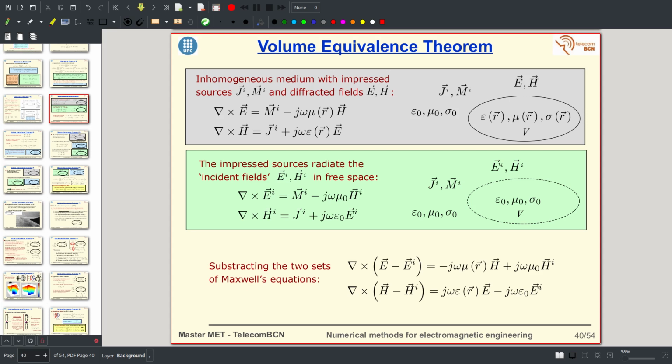using linear system theory, in which the output of a system is the convolution of the impulse response with the input, which is valid for invariant systems, time invariant systems in the time domain, or space invariant systems here. And a space invariant system here means homogeneous space. So as a consequence of using the convolution with the Green's function, which is the impulse response, we are restricted to computation of electromagnetic fields due to currents only in homogeneous space, usually free space, but it can be any other medium.